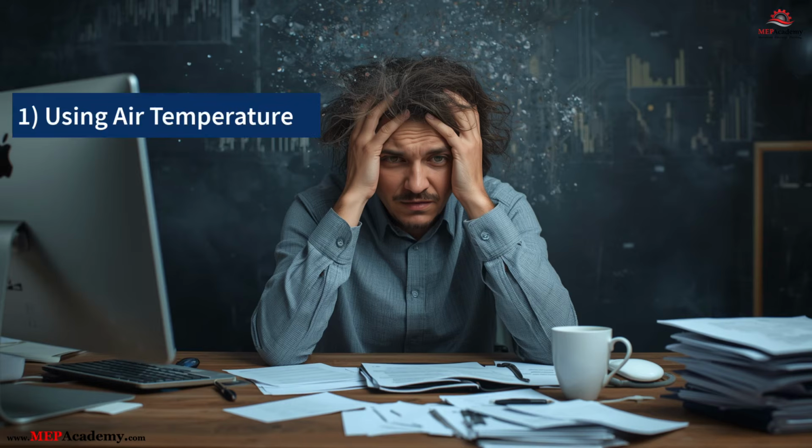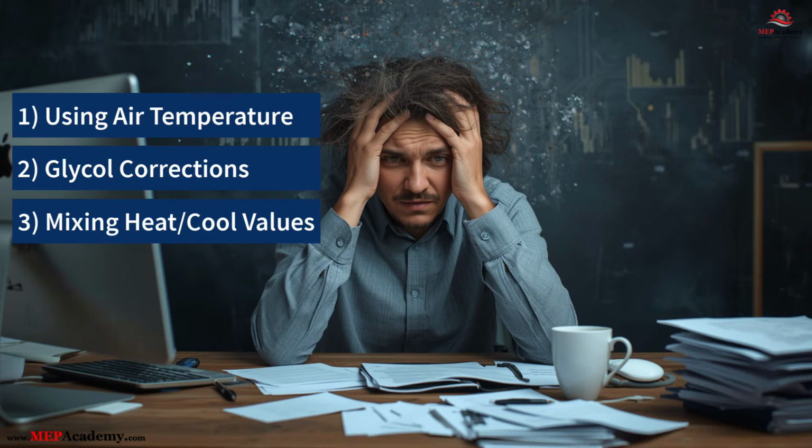Common mistakes to avoid. Here are a few common mistakes people make. Number 1. Using the air temperature difference instead of the water temperature difference. Number 2. Forgetting glycol corrections. A 30% glycol system reduces the multiplier from 500 down to about 450. Number 3. Mixing heating delta T with cooling delta T. Cooling coils often use 12-18 degrees Fahrenheit. Heating coils often use 20-30 degrees Fahrenheit.